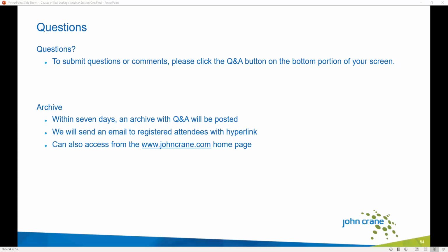Yeah, so I think most people who have worked with mechanical seals for any amount of time have probably noticed that carbon is a very common material for the primary ring, and there are a number of reasons for that. With all materials for mechanical seals, and definitely with materials for the faces themselves, manufacturability is one of the main points that we want to look at. So are we able to form it into the geometries that we want? As Stuart mentioned, the primary ring typically has the more complex geometry. We're designing it in certain ways to be able to handle the closing and the opening loads that are being imposed by the pressure within the process fluid. So our ability to manufacture it is a big point.